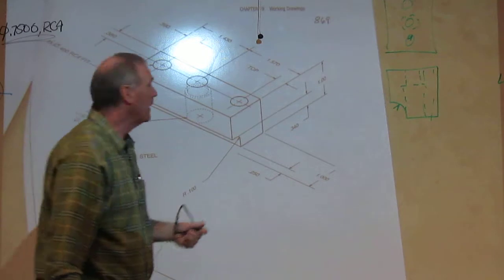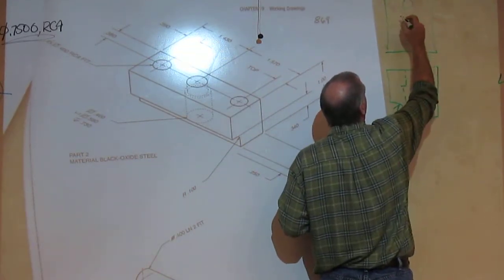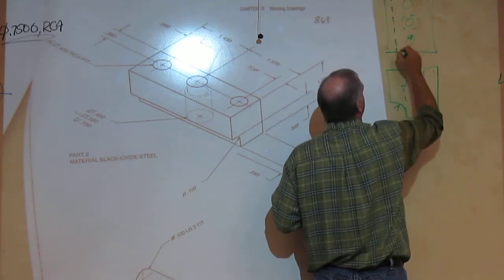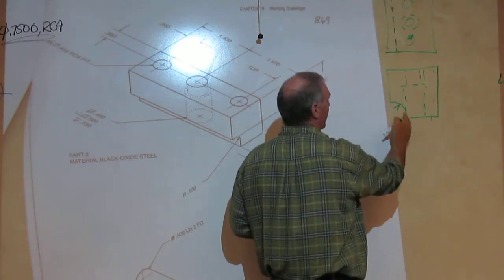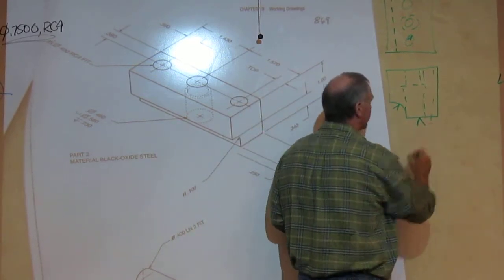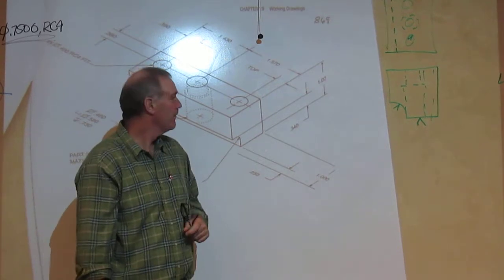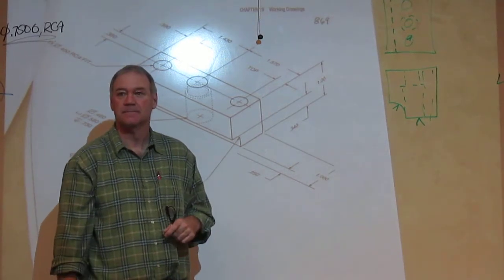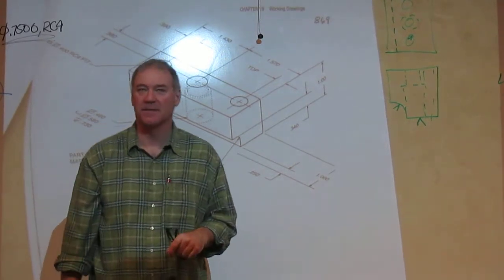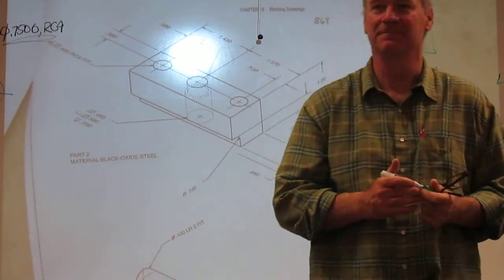All the surfaces. No, I don't think this one mates, because you've got this little one. This is the mating, right? It's mating with some part you're clamping. Oh, okay. This would be a finished surface because that's mating with the lower block. So if it touches something else, basically. Yeah, it's got to interact with another surface.